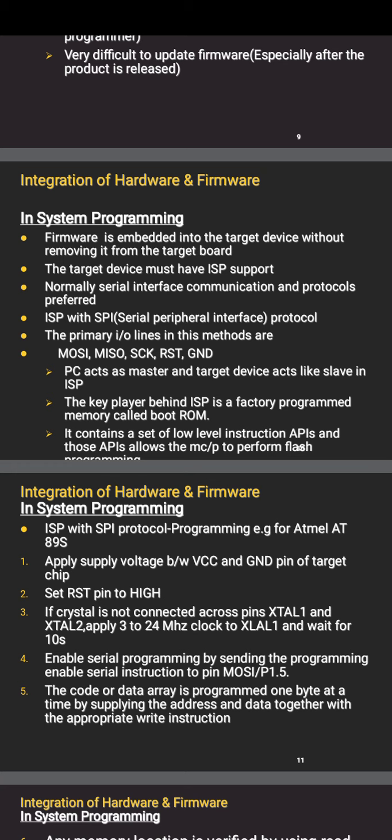Here the target board itself is connected with the computer either through the serial port or through the USB port, and there is an in system programming utility program in the computer, and this utility program will help in embedding the firmware into the hardware.